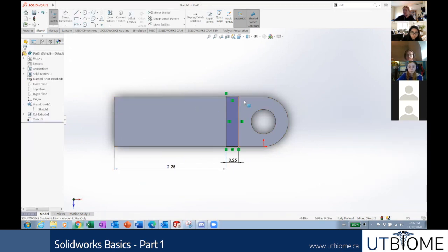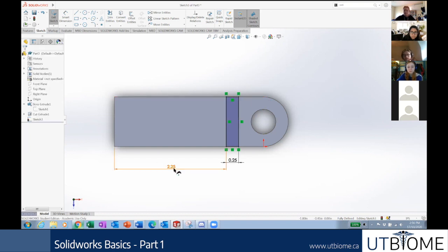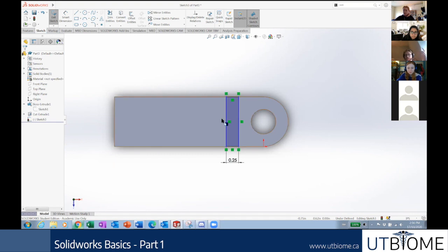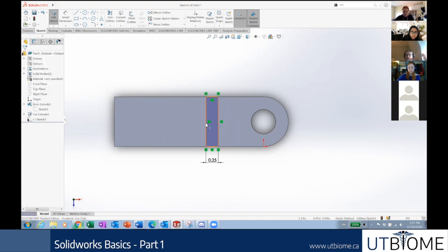And if you want to confirm, it's a great practice in SolidWorks to grab your model, or what you're sketching, and try to pull it. Just like when I didn't have this dimension here. Okay, let me click this the way I want to click it, SolidWorks. Just like before, I saw that there's blue, so I know that there is something that can still move. It's very useful to just click on it and hold and move it so that you can know exactly where you still need to define things. Because otherwise you could think maybe it's the height that needs to be defined here, but no, we find out that it's this distance.